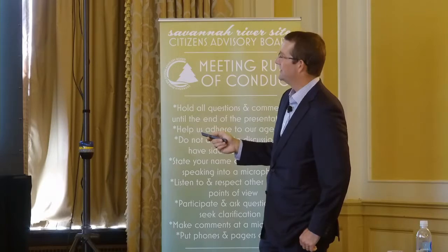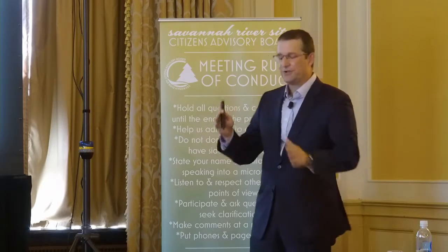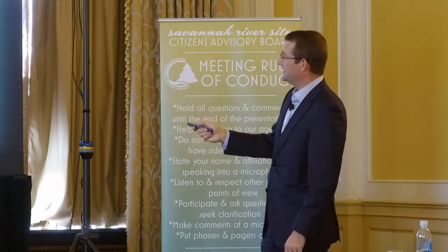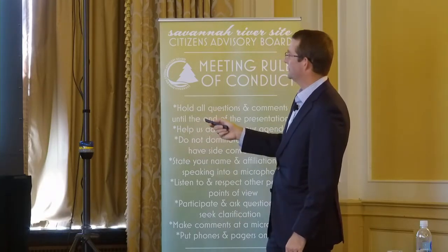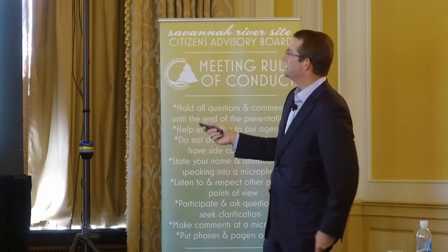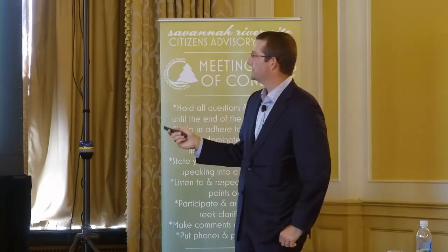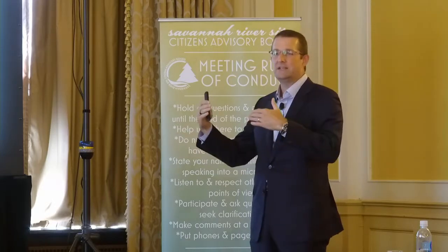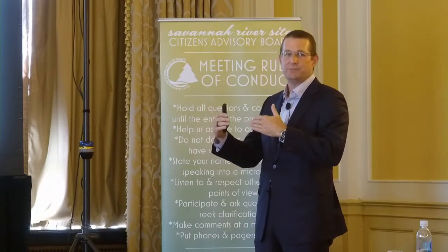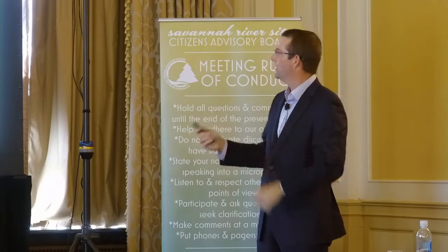So dry material comes in here. It falls onto some screw feeders that move everything forward. Then you have the liquid introduction, and I think the liquid introduction is actually right about here on this picture. And then you can see within the mixer there's 2 shafts with mated paddles at each location. And so these shafts co-rotate.